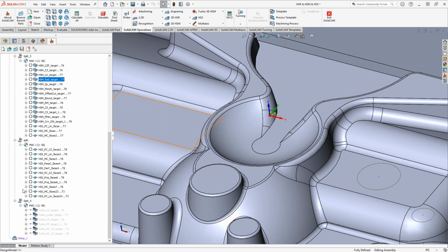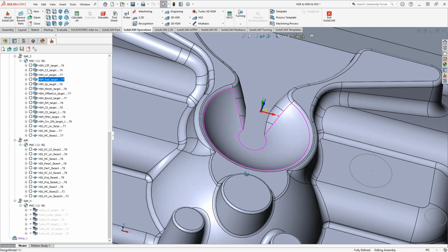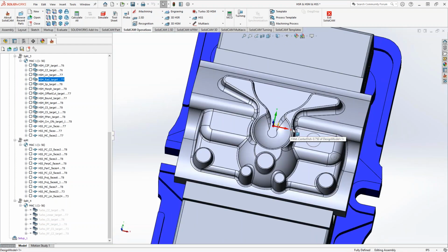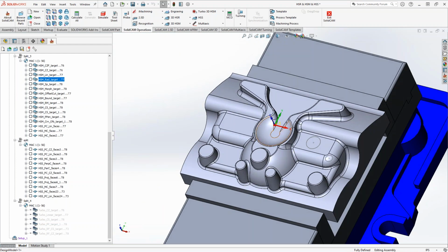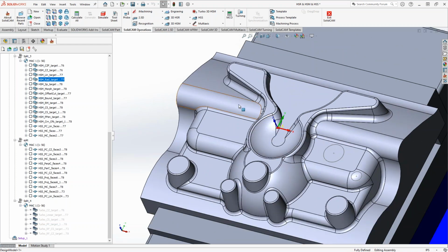Whereas if you really fine tune where you want the toolpath to go, you can trim your toolpath. Going back to what we talked about at the beginning of the class today, trimming toolpaths, reducing cycle time by movements, and you can probably get a better finish as well. Because if we were to use multi-axis constant stepover, we would be moving in all directions, maybe even spiraling out, depending on what it analyzes from the solid, and that's not going to be necessary for every one of these surfaces. I don't need a 90-degree turn on this surface when I could just do linear and get a nice smooth toolpath that goes back and forth. So a lot of those toolpaths that do the whole thing, the set it and forget it sort of toolpath, get the job done.